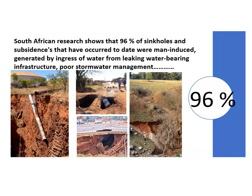Picture on the right-hand side is more to do with natural sinkholes forming. So if you look on the top of that picture, you'll see there's like a little tree. That's obviously not the tree that's dead, that's lying in the doline or the sinkhole, but the topography is basically so the ingress of water has been running down over a couple of years or a couple of tens of years, and obviously it's run to a point where it then ponds up and then it just leaches into the subsurface, and into the soil, and eventually with maybe a bit of dewatering or anything of those kind of things, it starts to then cave in.